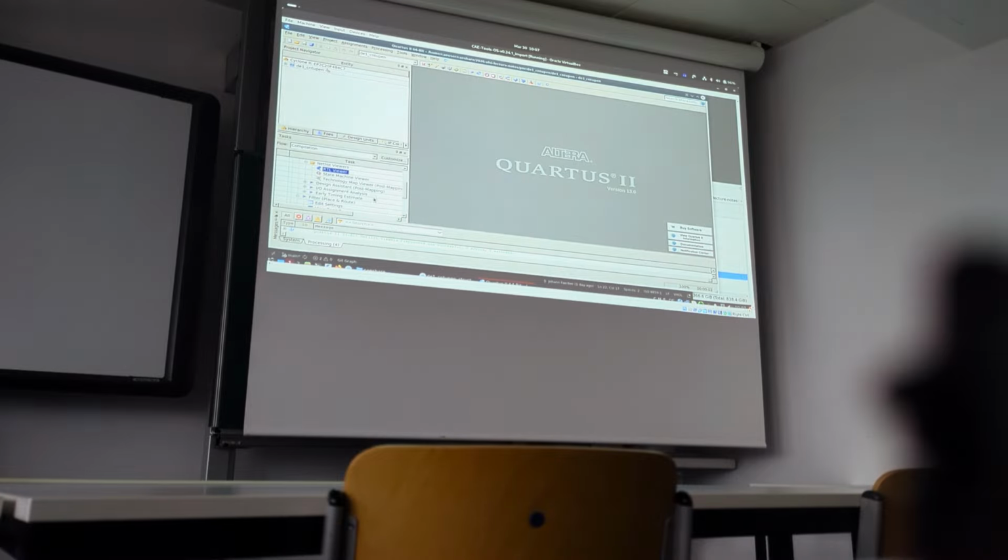There is another viewer which is called technology map viewer. Typically, when we run through the different steps, which we normally do not using the graphical user environment, we are doing that with a makefile, because normally designers do not work with these graphical user environments, just in special situations. So if we go through the different parts, analysis and synthesis, and then the fitter, the so-called place and route, where the elements are placed on the chip.